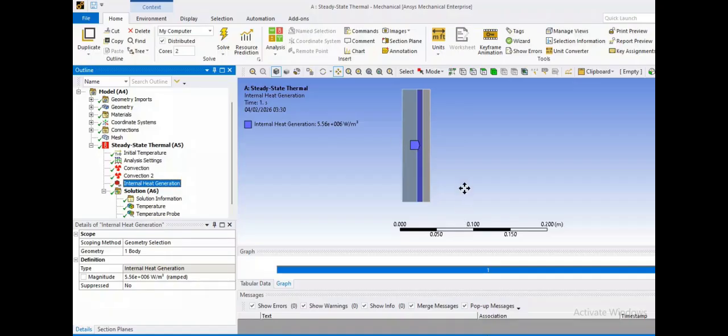Area is the 15 by 15 cm, and the thickness is what I use for this particular length here at this base, which is 0.08. So once you multiply 0.08 times the area given to us, that's 15 by 15, you will get this particular value. Let me state it again: internal heat generation, that's q, is equal to the heat flow divided by the volume. So once you do that, you'll be able to get this particular value.